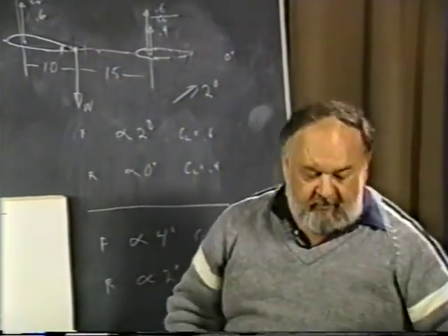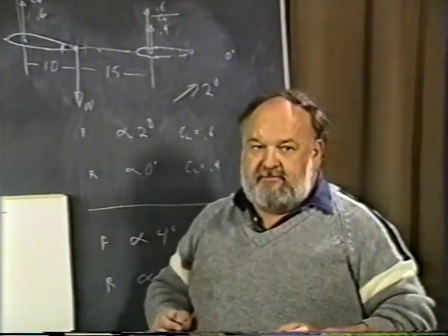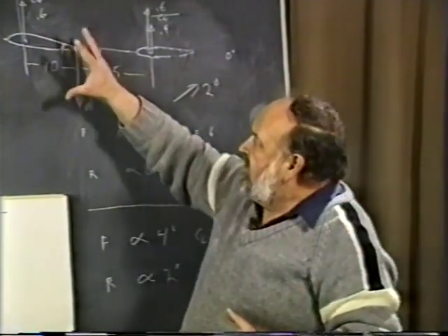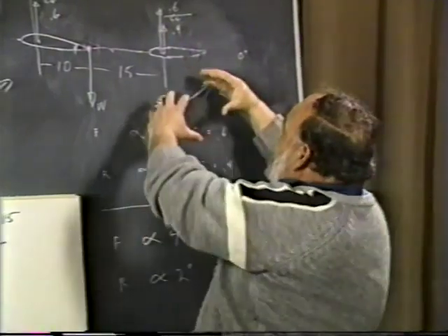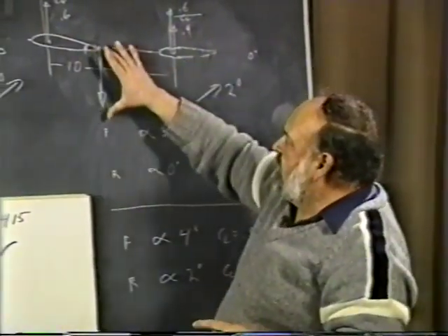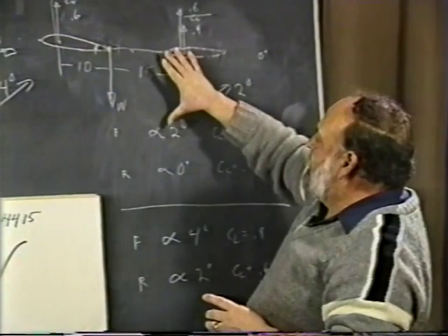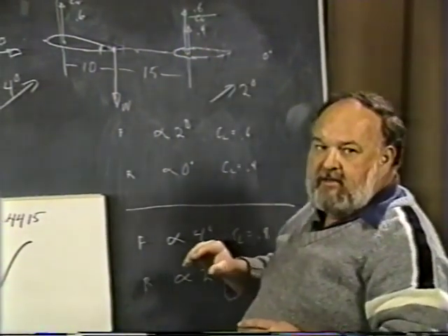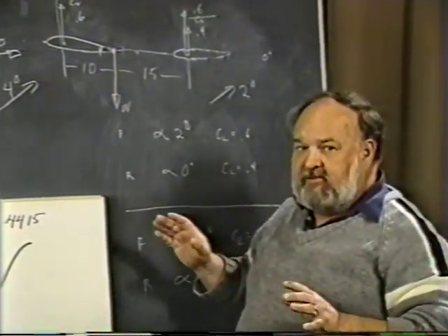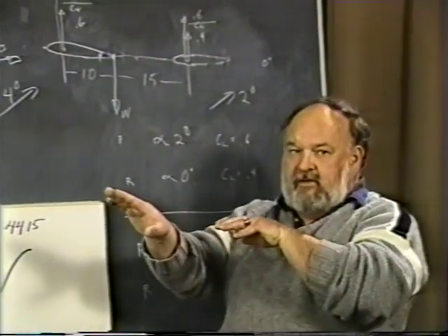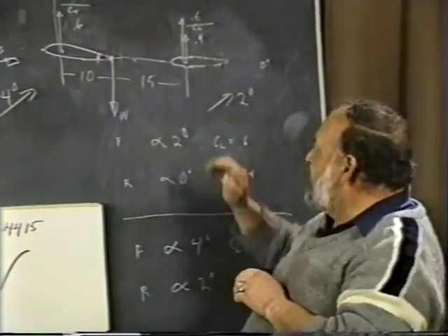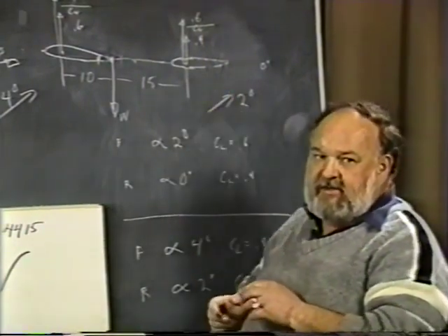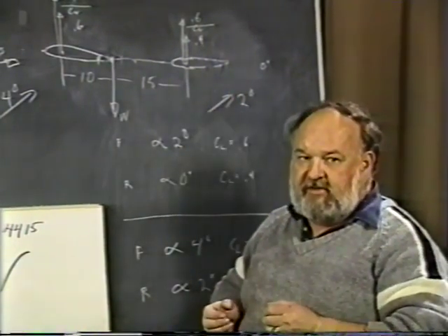Now, if this is a canard airplane, it's all right. You've made this surface smaller and smaller, and this one bigger and bigger. Your total lift on this one is very large, so your balance point, your center of gravity, has to keep moving further and further back. But the same fundamental things must exist. When you're flying along and a gust hits you, this will increase in lift, this will increase in lift, but this one has to increase in a greater percentage of lift than the front one.